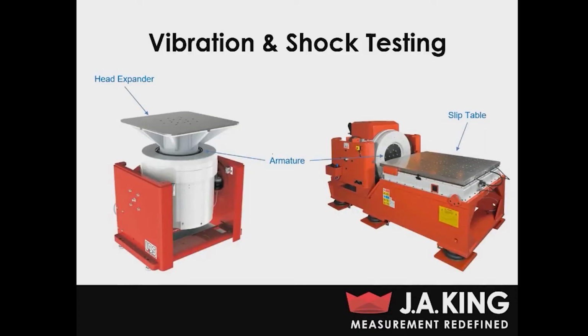So I also want to go into just some basic vocabulary about the actual shaker system itself. You'll see here I've pointed out a shaker in both the vertical and horizontal orientations. The armature is the moving member of the shaker, and this is what's actually going to transmit vibration into your fixture and your DUT. The armature is going to be bolted to, a lot of times, either your head expander or your slip table, whether you're in the vertical or horizontal orientation. And the point of the head expander and slip table are both essentially just to give you a larger working area to bolt your fixture or DUT to for vibration testing.